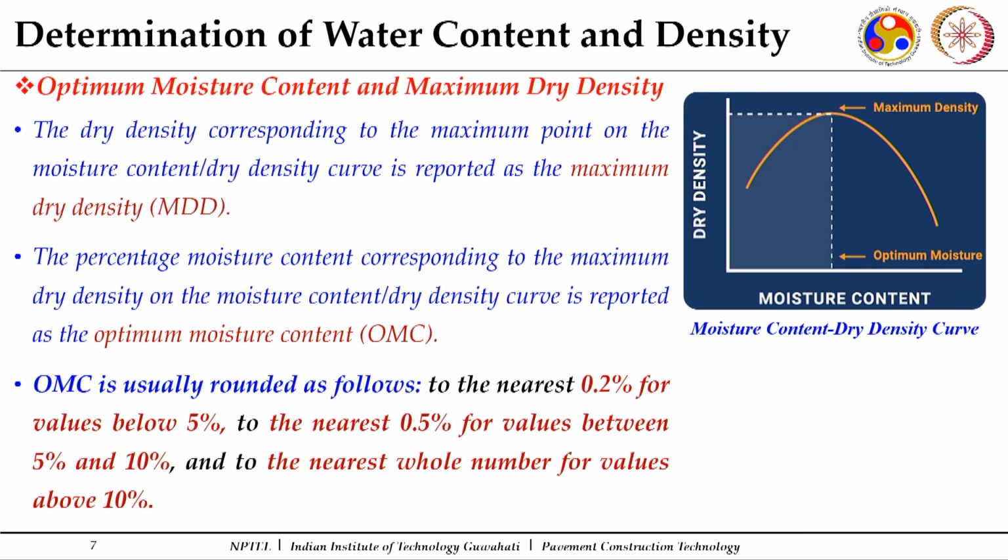And finally, what you get out of it? You get a curve between your density and the water content. The density which you get out of this measurement is your wet density, and the density which is finally used here is your dry density, which will be your wet density divided by one plus water content over 100. So, what we refer to here is the dry density.